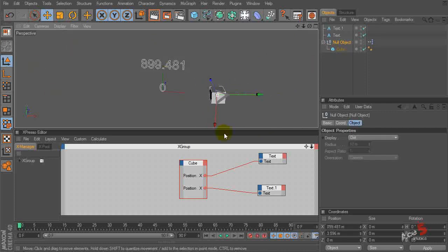And using a range mapper, you can feed it into percentages and stuff. So if you have some kind of crane or anything that's moving and you want its angle of incline to be displayed on the screen, you can plug it in like this and you have this dynamic number which tells you how far it is.